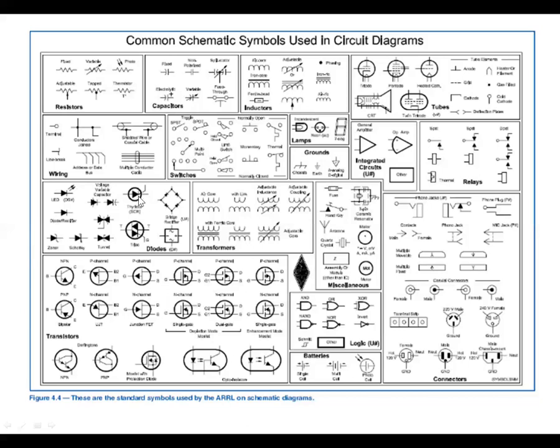This is a thyristor or silicon controlled rectifier that will flow current in this direction as long as it's biased that direction, and you have a gate current that turns it on. So this will actually block current in both directions unless you provide the gate current. You'll see this next